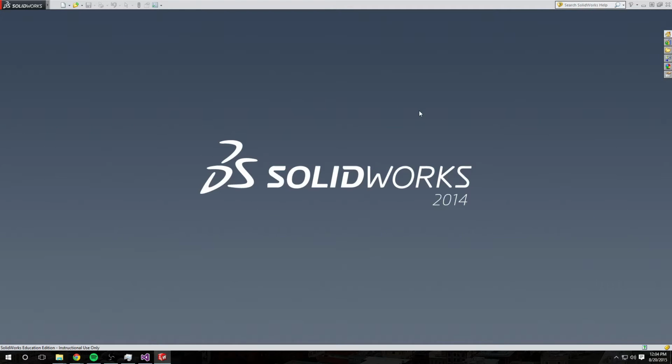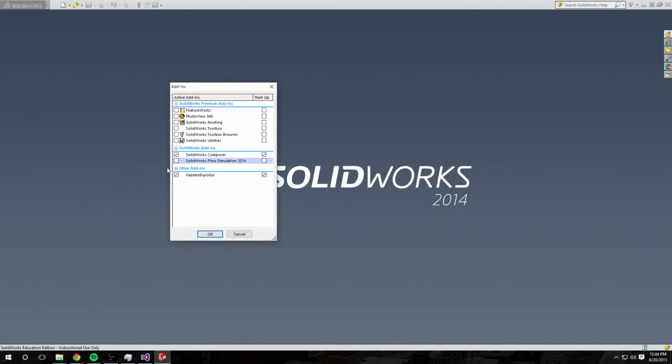Once you've installed the exporter, the first thing you want to do is make sure the exporter is enabled. You can do this by going up to Add-ins and making sure this checkbox here is checked. You're going to want to make sure you do this before you launch or open any document that you want to export. If you want to enable the plugin to launch on startup, you can also check this box and it will launch as soon as you open SolidWorks.